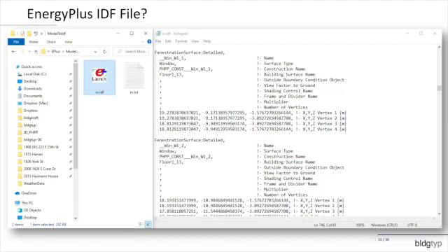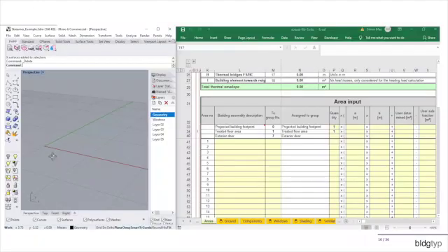And this IDF file is what Honeybee is actually creating. So that Honeybee tool creates this IDF file, and then you can go execute it however you like to execute your Energy Plus simulations. You want to use EP Launch, you want to use Open Studio, whatever. You can then run these energy simulations however you like. But for our purposes, what we want to do is take all this information and pull it into a PHPP. So we get this matching PHPP, which is built off the IDF2PH.